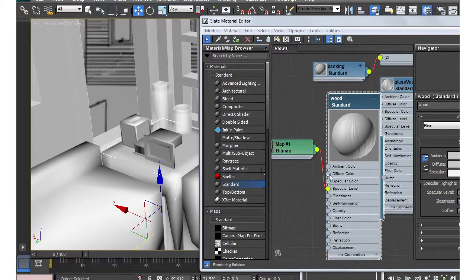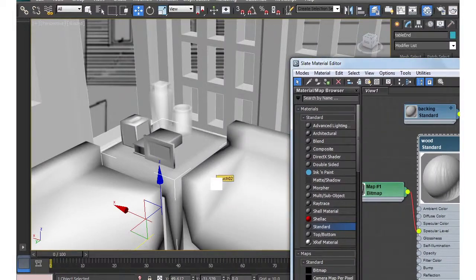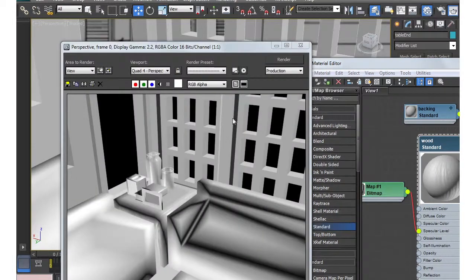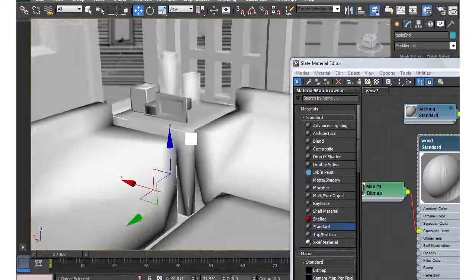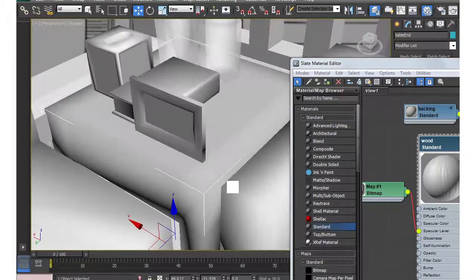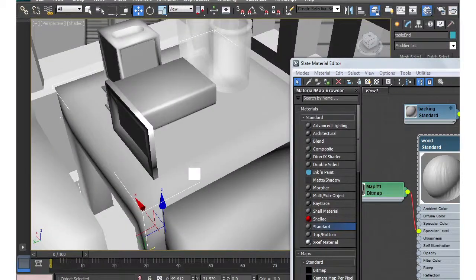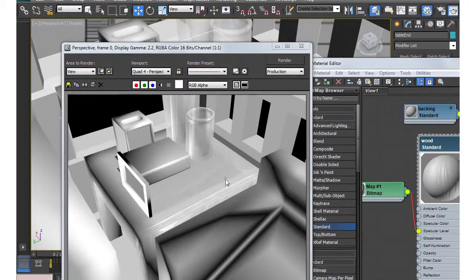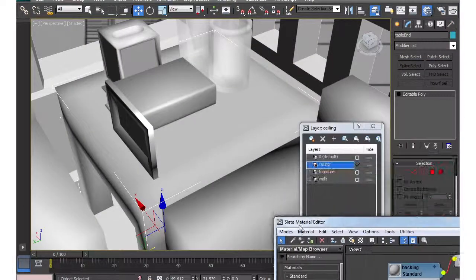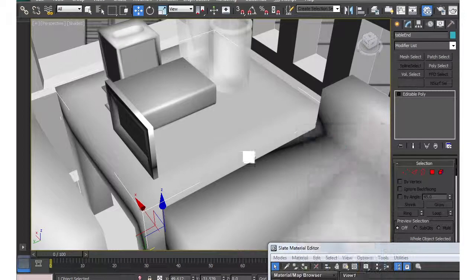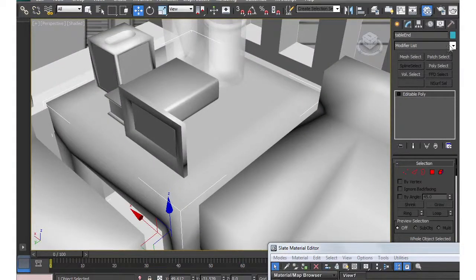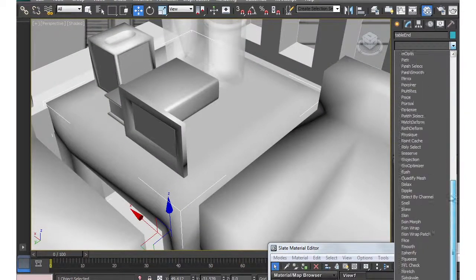If we grab this table and wire it on, and then hit Shift-Q for render, we can begin to see some wood in the detail, some of the grain, the way it reflects light. And importantly, as the camera moves over the surface, that will change. In order for that to display properly, we should apply a UVW map.